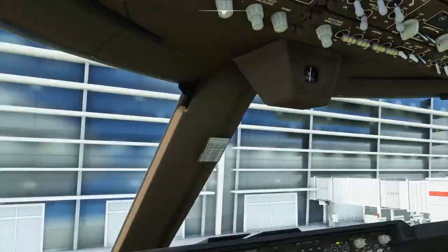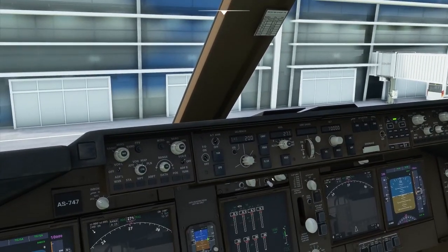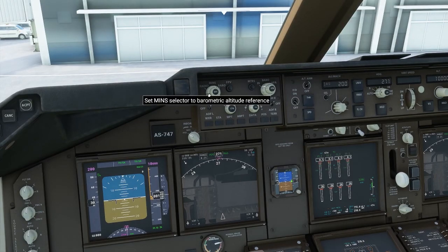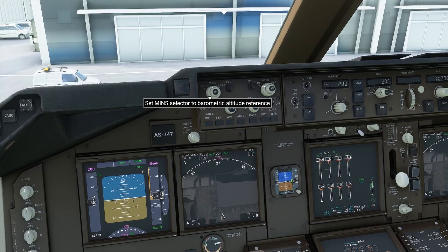So yeah, then we've got your compass. You come down, and then you would do your AFIS control panel. So you would set up your baro or minimums for your takeoff. So you could set these, normally they're set to 1,000 feet above airfield elevation, but for some reason the switch works, but it doesn't work on here. So I've tried figuring that out, but haven't got there yet.